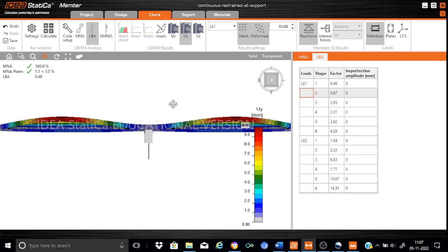And here, what is very important is that if the support conditions are the same, it means that we have to revise the IP300 to some other higher size, IP450, or another possibility is to keep IP300 and introduce an additional beam at the midspan. This exercise, wherein we will introduce an additional restraint at the load application, will be covered in the next tutorial. And in this tutorial, please remember that we have added a restraint only at the support location.